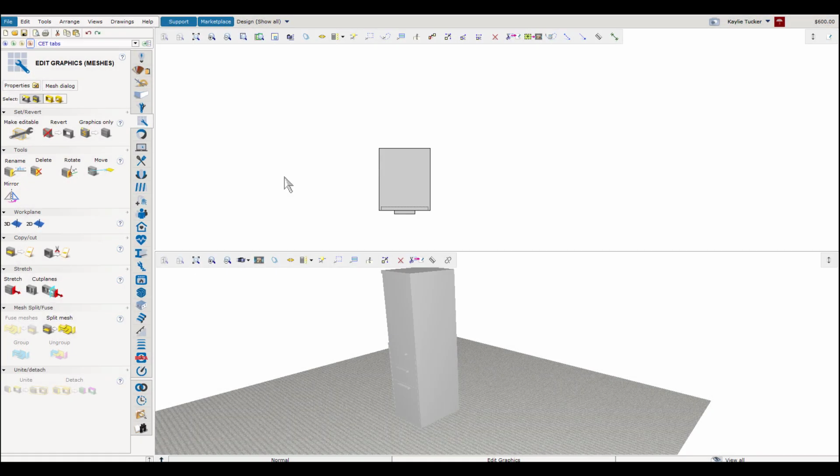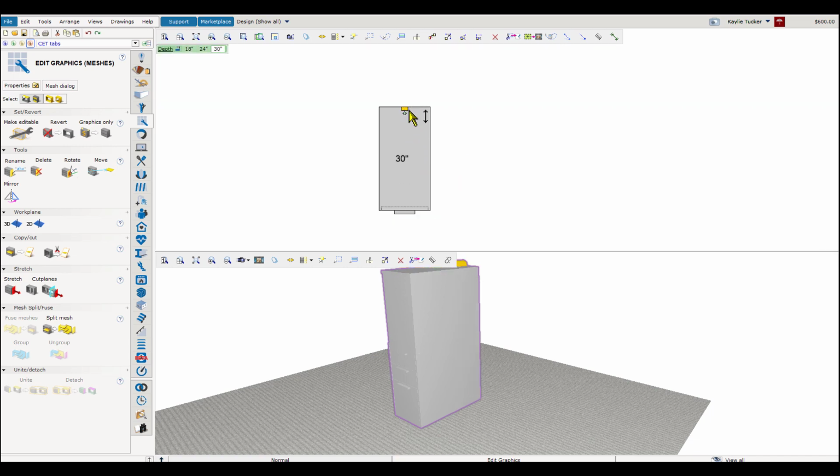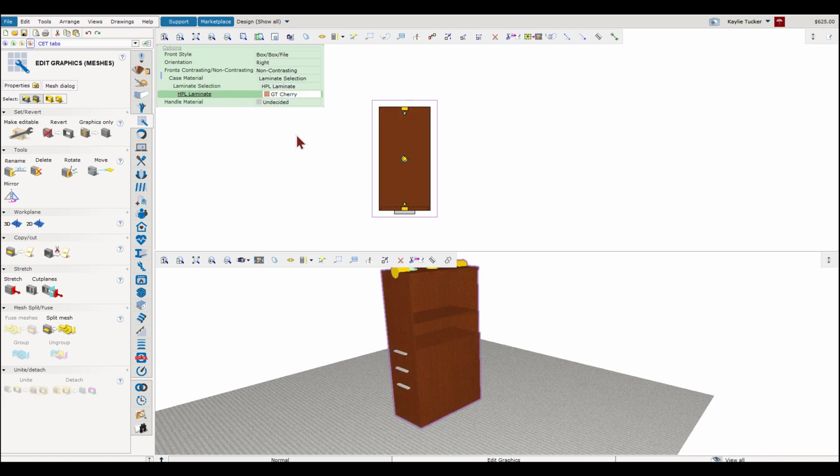Well, isn't that special? Best practice when you're creating a special is to have a component in my drawing and get it as close to the final item as I can. So I'm going to do things like stretch it out, select the right hand side, and also select finishes. If they're not special finishes, I could select some standard finishes that are available to me. The goal is, again, to get it as close as you can to your final item. It's not impossible to make these changes at the end, but it makes your life a little bit easier.